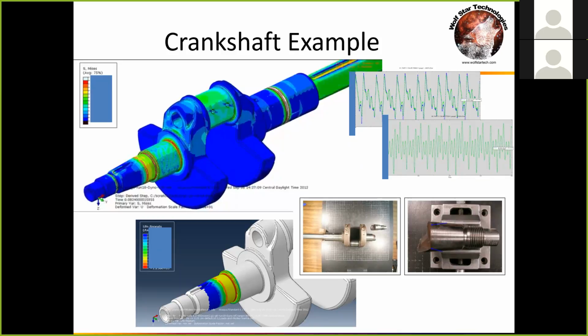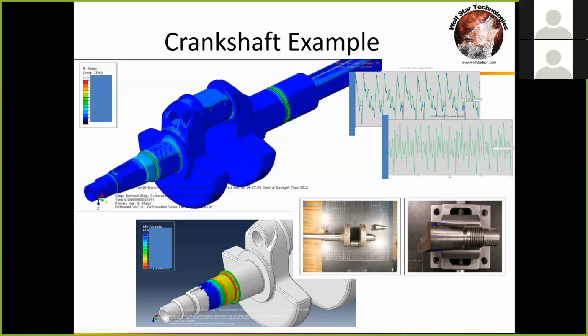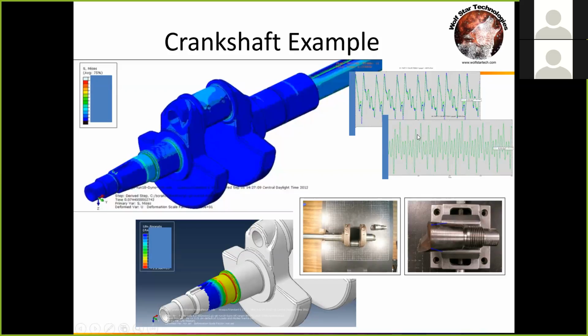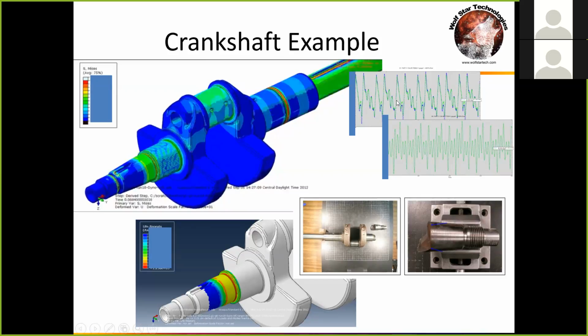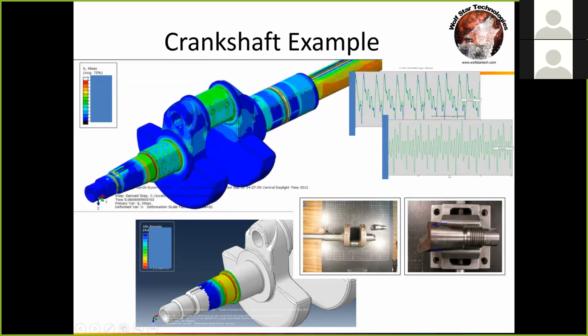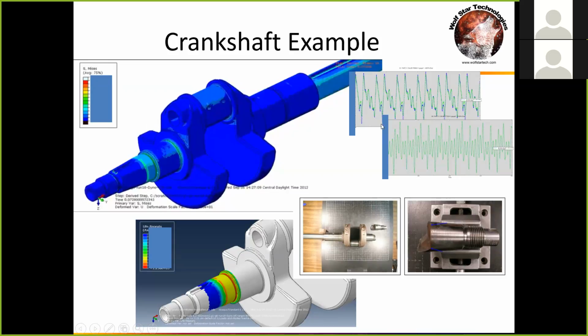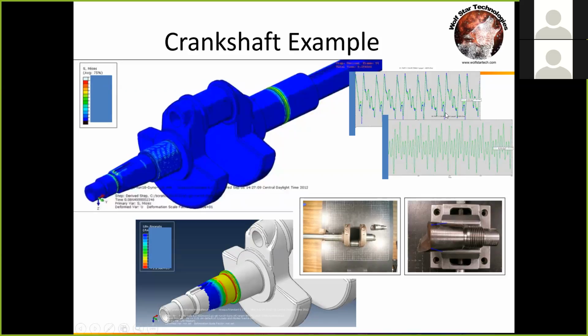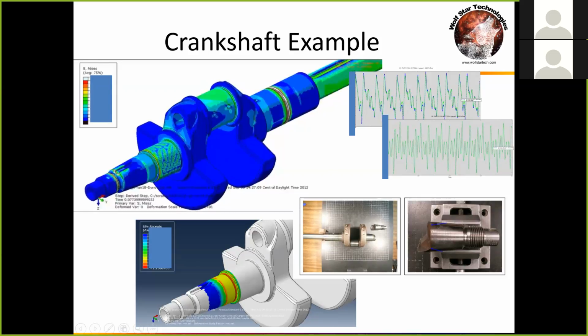So we had five unit loads. We laid strain gauges on here, and what you're seeing on the top right are what I'm calling my bob and my wow plots. So best of the best, worst of the worst strain correlation. Green is measured, blue is simulated here, showing that we're line on line, like 0.01% error. And even my worst gauge, it might be 1% error. Okay, so this is how well we get with strain correlation.